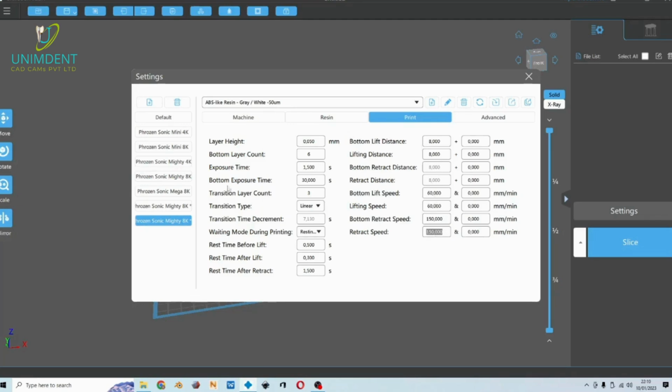And from all the settings here, some factors for how long your print time will take are the lift distance, and then the rest time, the height of the object, and also your speed. And from those four, rest time and lift distance are the biggest factor. To keep the video short, I will explain more in a future video, but you should try changing the rest time and the lift distance and see how much difference they make. Speed only has a very small difference to print time.